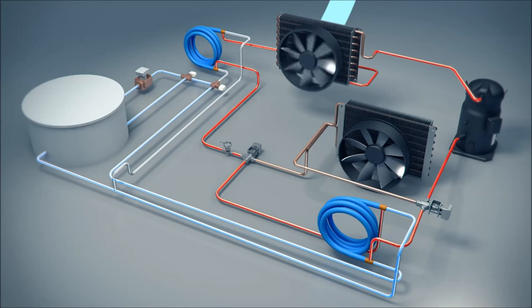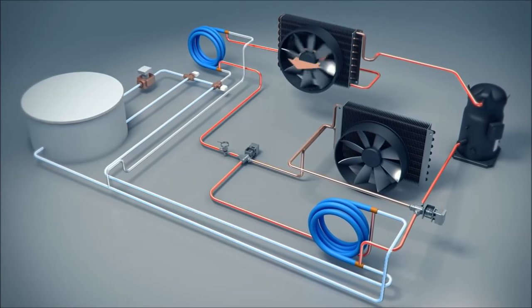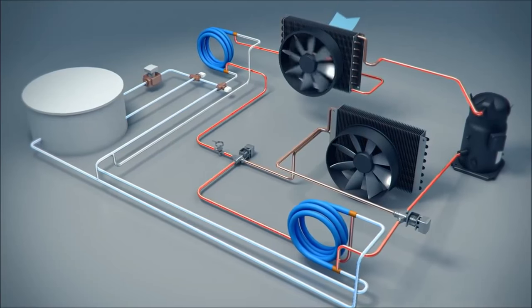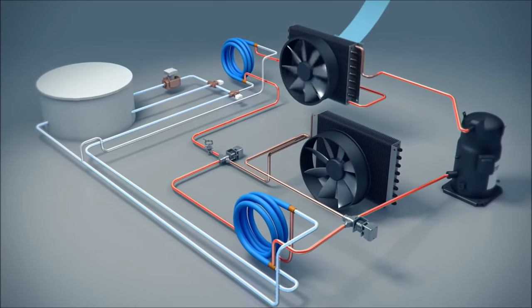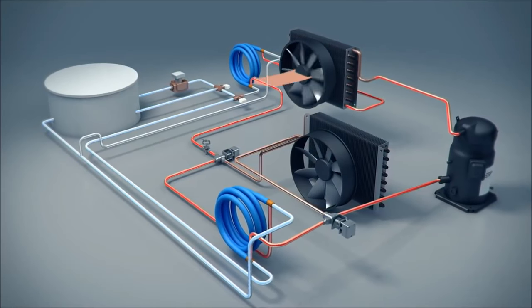Exiting the valves, the glycol re-enters the AC Companion heat exchanger, whereupon the charging process is repeated. The System Logic controller monitors and controls the AC Companion charging loop to ensure a complete phase change within the ice storage vessel, whereby the system is shut down in preparation for the following AC Companion stabilizing loop function.